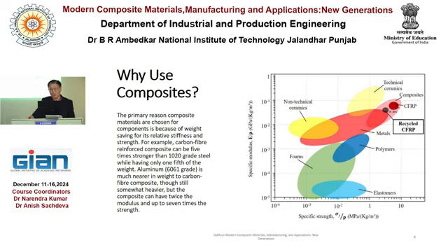A high Young's modulus line means high stiffness can be held. This metal group is weaker and lighter. But lighter with higher strength can be found in this group, which is beyond the metals. And this part is the carbon fiber reinforced polymer, CFRP.